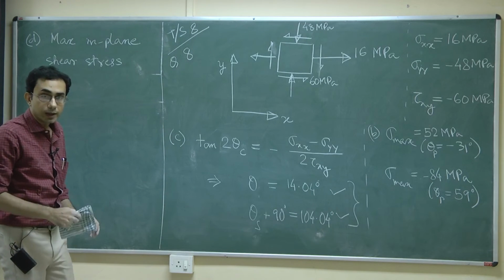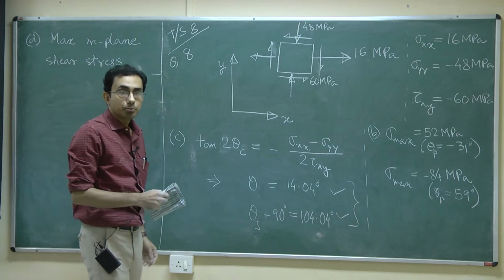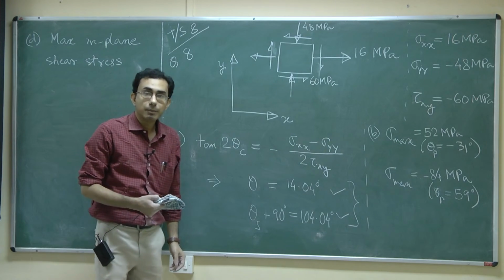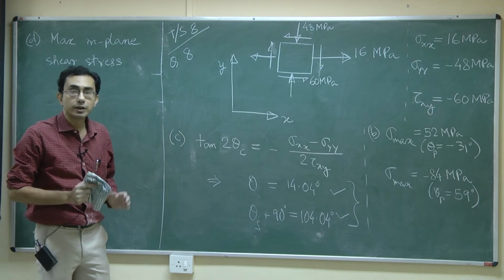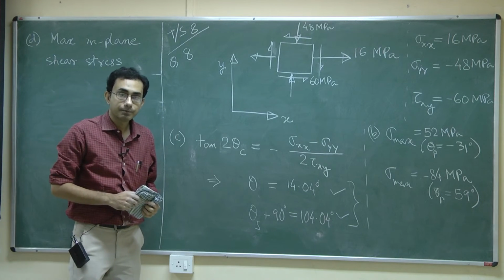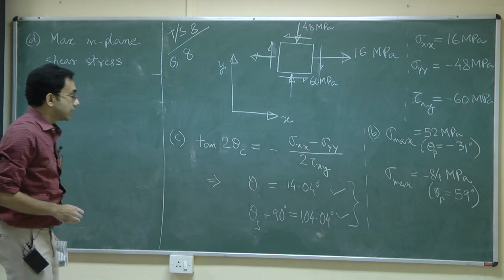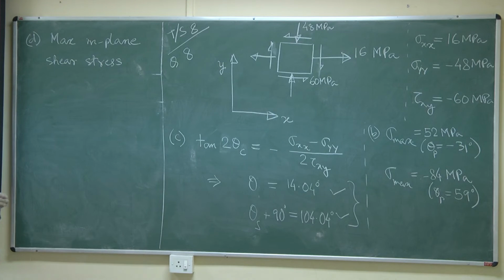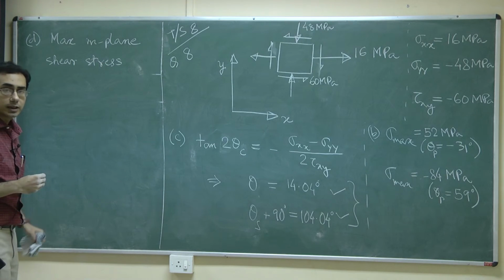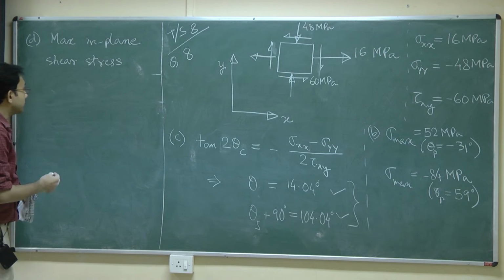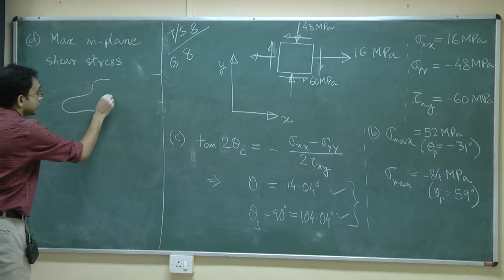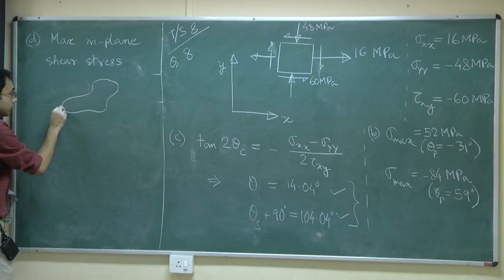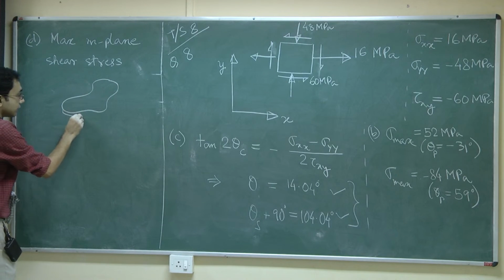Today when we obtained the principal stresses as well as the maximum values of the shear stresses, all of this was within this universe of plane stress. But suppose you tilt your orientation a little bit, or you open your mind a little bit to the actual three-dimensionality of the situation. Let us appreciate for a moment the three-dimensionality of the situation.